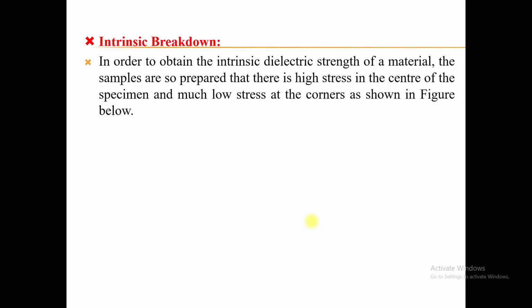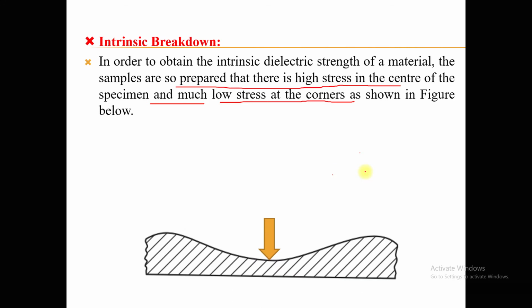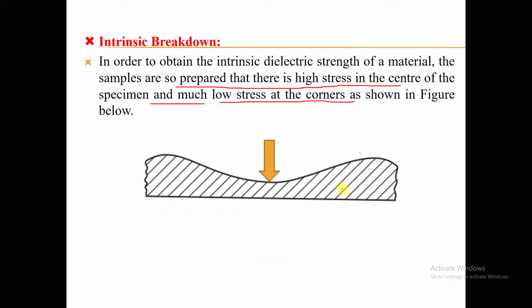So to obtain the intrinsic dielectric strength of a material, the samples are so prepared that there is high stress in the center of the specimen and much lower stress at the corners. You can see them in the figure. Here you can see that the maximum force is applied exactly to the center just to determine its intrinsic strength, whereas as I move from the center to the right side or the lower side, the stress is gradually reduced.